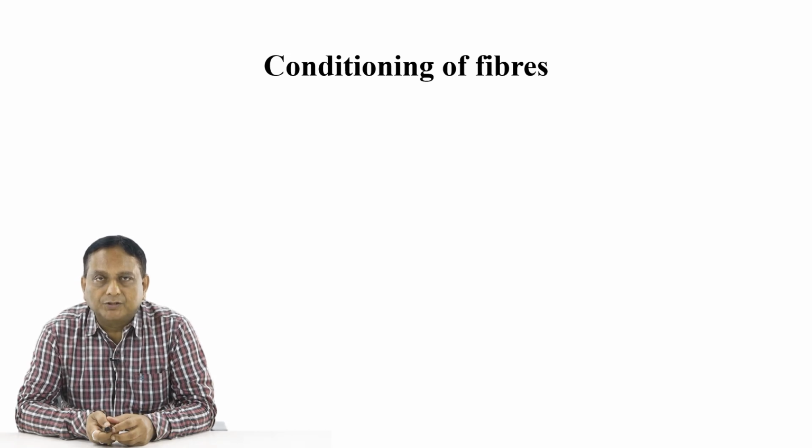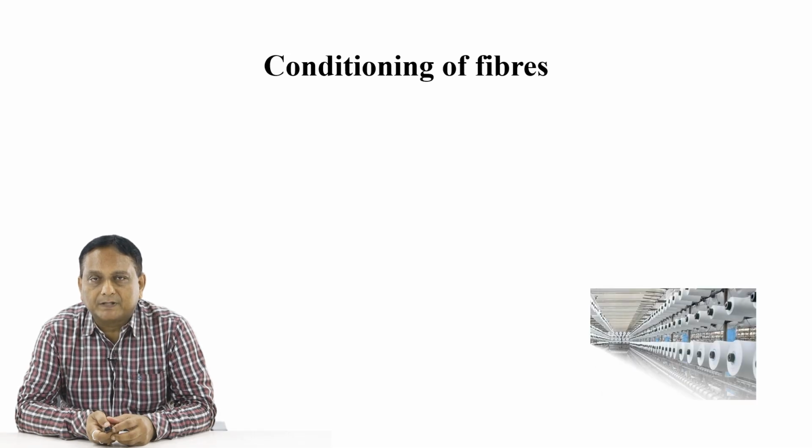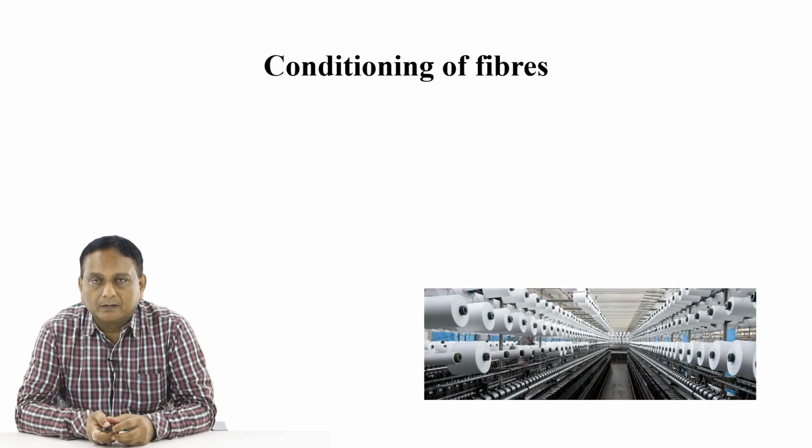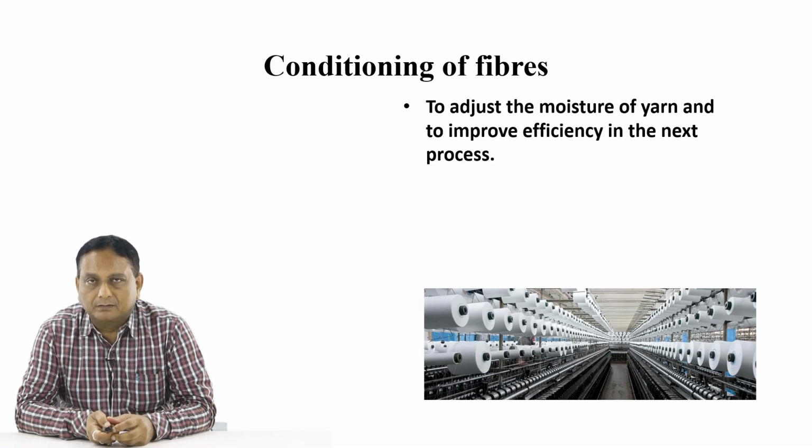Now what is the conditioning of fibers? It is very, very important to understand the conditioning of fibers, because textile material, being hygroscopic, normally attracts moisture. Many of the processes, as shown in the spinning zone, are also regulated by the condition of the fiber. So to adjust the moisture of the yarn and to improve the efficiency in the next process, the conditioning of fibers plays an important role.